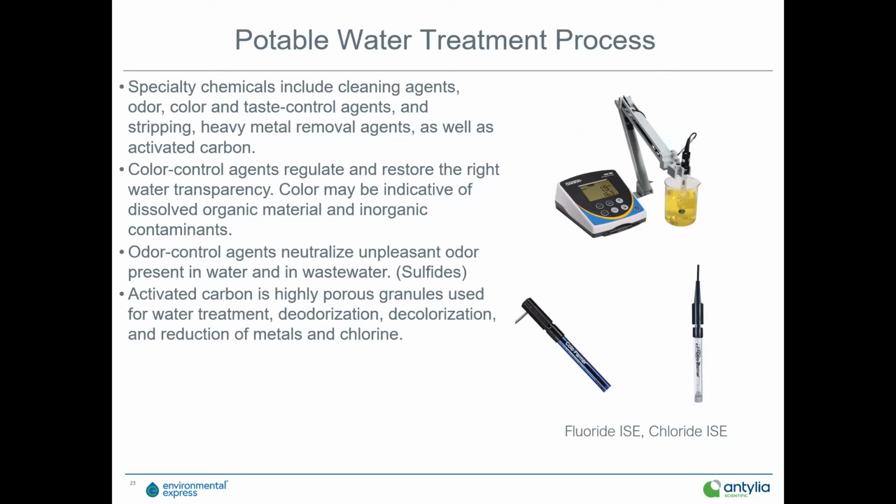They changed water sources, and I'm not going to speak to the detail of it, but essentially the water chemistry was slightly different. I don't believe they used a passive inhibitor on their pipe, and the new water started leaching iron and lead contaminants from their existing piping. So that's a big deal.